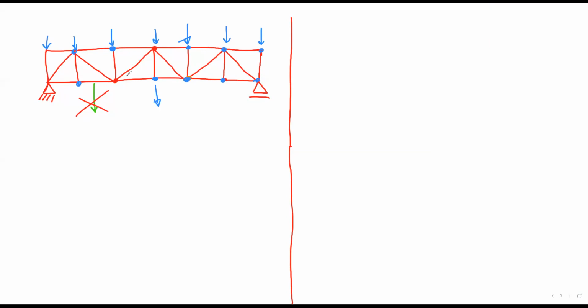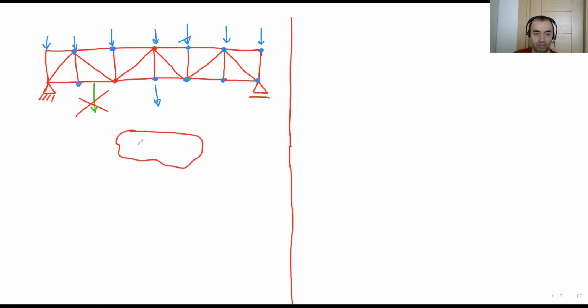If the roof is a truss system, as an architect, you have to connect these. For example, we have a decoration here, something else, I don't know. You can't connect this directly to the midpoints. No, you have to do this. You have to connect all these members to these joints. We only transfer the loads from these joint locations. Don't forget this one.